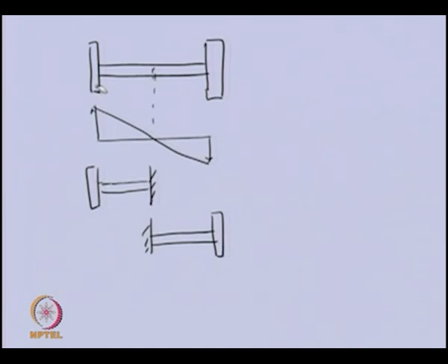So, a 2 rotor system which is a 2 degree of freedom system can be idealized by 2 single degree of freedom systems, and in this case they are cantilever rotor systems, and both the systems should have the same natural frequency, because when we consider the motion, obviously for the second mode both the discs have the same angular frequencies.